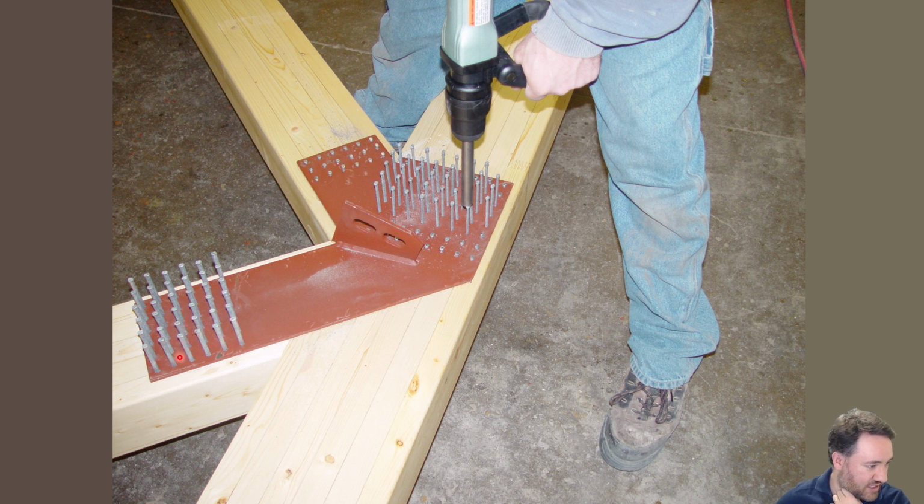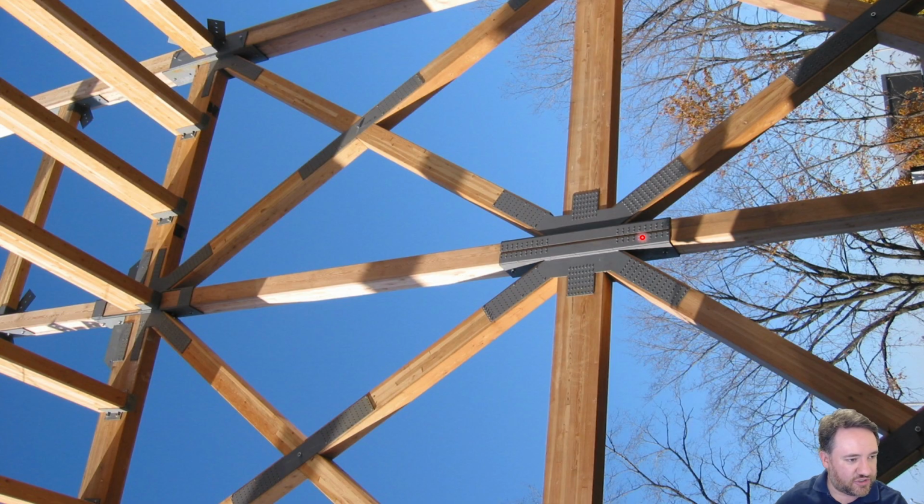These rivets, you can see a little bit how the head is elongated in one direction. And these ones are lined up with the grain in this piece of material. These ones are lined up with the grain in this piece, and these ones here are lined up with the grain in this piece when they're installed. And this can look very attractive. We have some pieces of steel holding these big diagonal bracing members together, and timber rivets connecting the steel to the wood. And you use a lot of them, and you spread it out over a large area, and you can get a nice high resistance.